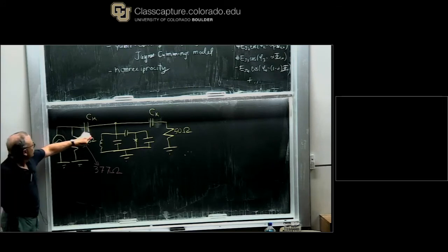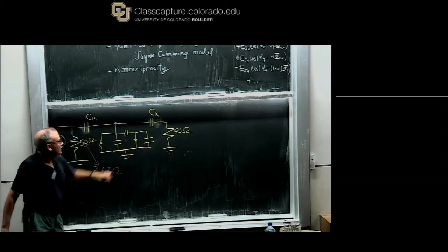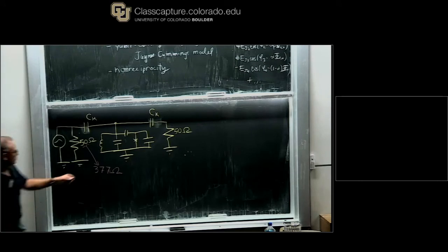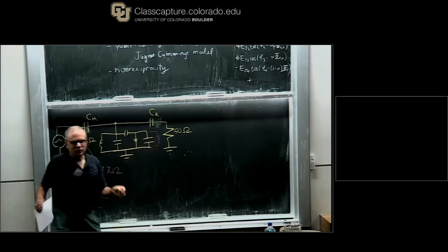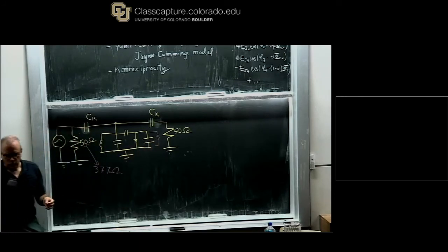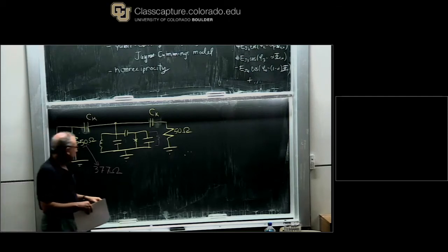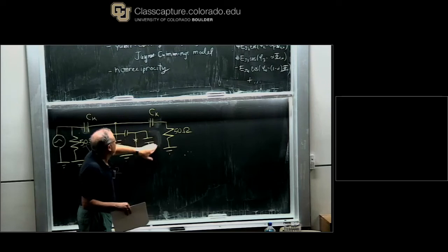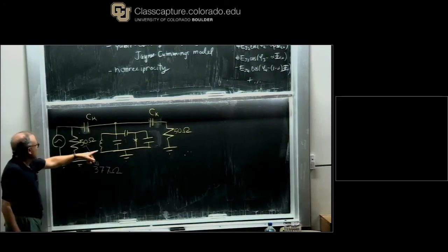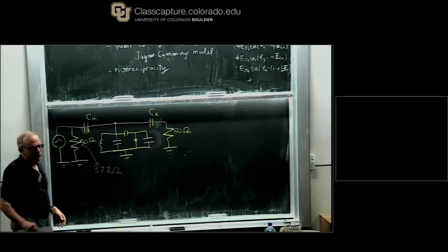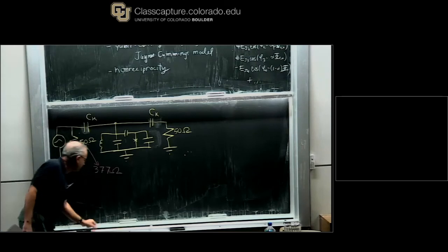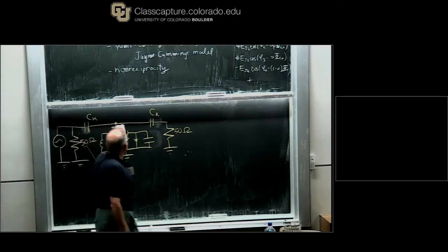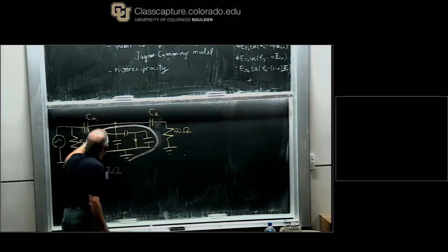However, you note 50 ohms is never seen by the qubit, and that's really important. If you put 50 ohms here, you could forget having qubits, and in fact that's sort of the regime of critical damping of the electric circuit, so that's surely not a good regime for having a nice coherent circuit. So you work really hard to not have 50 ohms anywhere near the sample, and you make sure you put big blocking capacitances between this device and the outside world. And so for that reason, in our quantization we won't go any further than this.